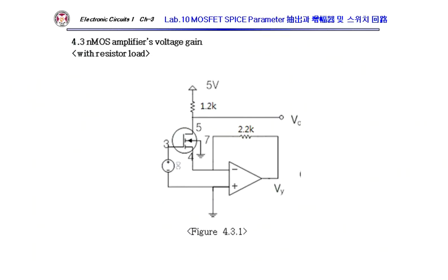Alright, so now we go to the amplifier. For the amplifier, I have to operate this MOSFET in the saturation region. Again, I have this negative feedback circuit. Then I have a virtual ground here, so this is 0 volt again.